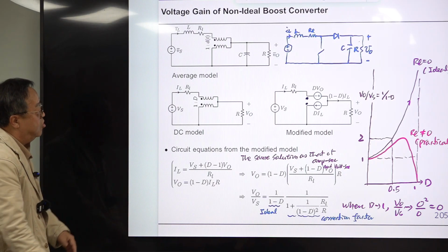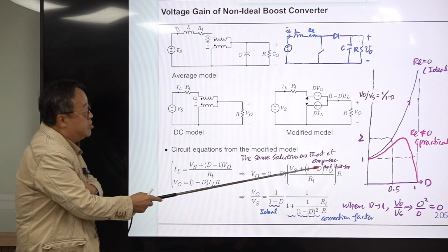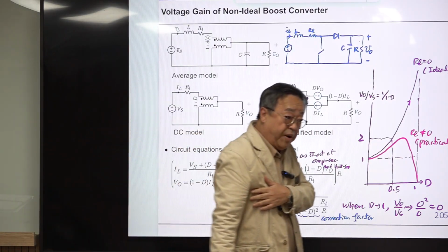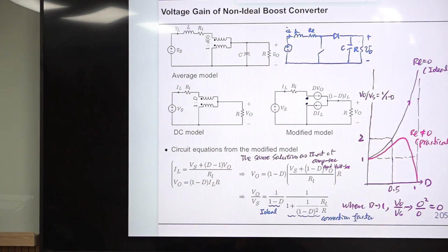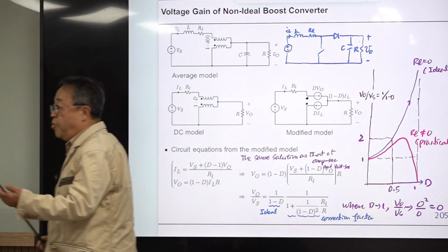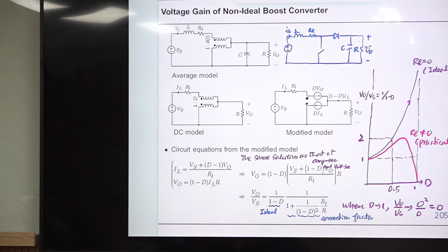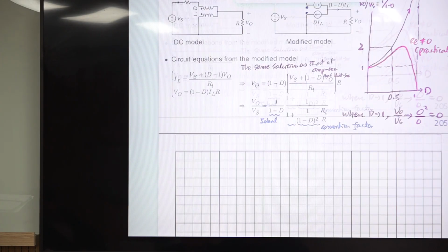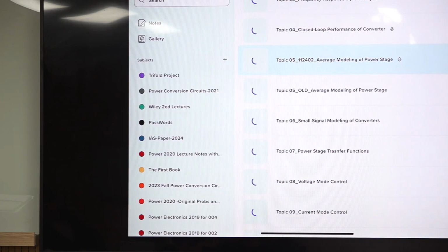At that time, we used the amp-second balance condition on the capacitor and the volt-second balance condition on the inductor, with 2 equations. We simultaneously solved those equations to obtain the same result. But this one provides some aspect of the property of the average model.